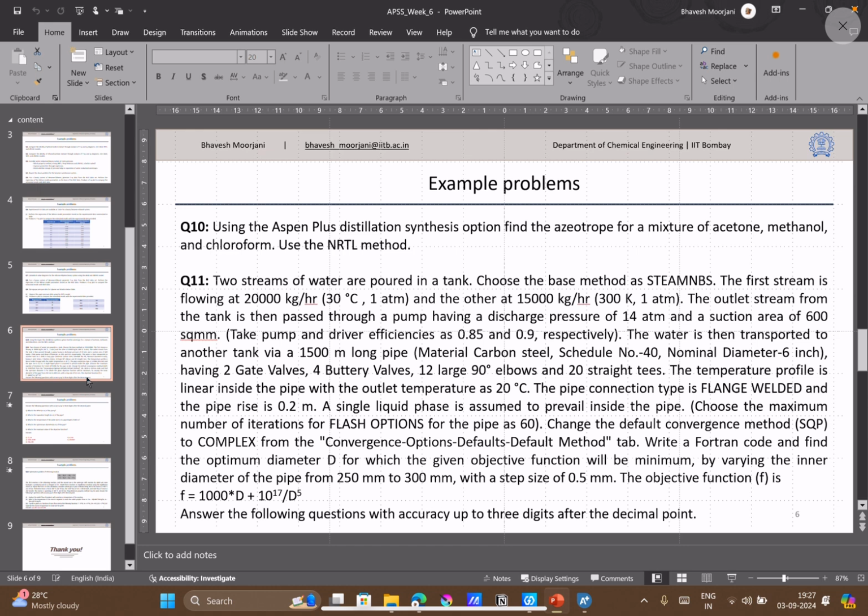Like all the models that we have seen, for the unit operation or unit process, the distillation column unit, flash column unit, reactor column unit, there also we can do sensitivity analysis. Sensitivity analysis is nothing but just variation of one parameter with another dependent parameter. Like in the pure component, we see the variation of density with temperature. This is a kind of sensitivity analysis, that is how the density of your pure component varies with the temperature. So the same thing can be done in our process analysis, and there it's called sensitivity analysis.